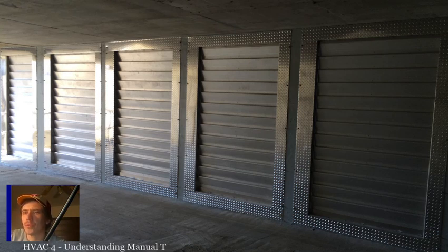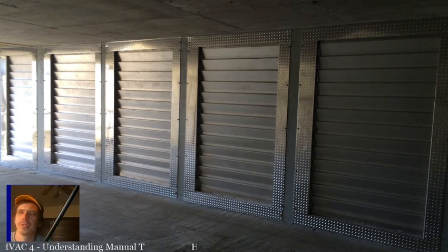The entire flue begins to get hot, and all the air tends to travel up and through the flue. When it first starts up, it's not hot enough to cause that stack effect, so you will get some spillage of combustion products into the room for a short period of time, but that should cease very quickly. So that's something to keep in mind.